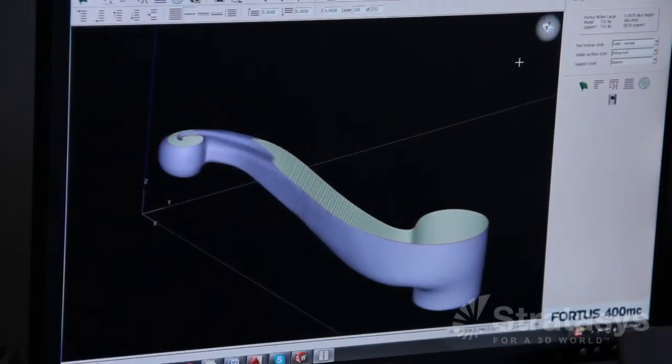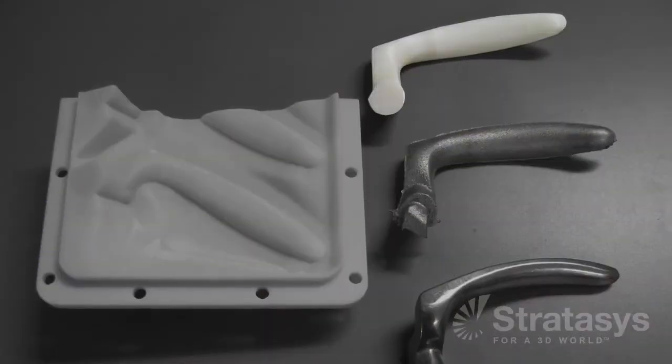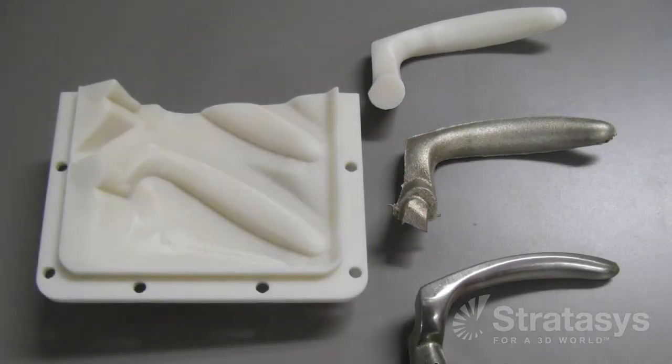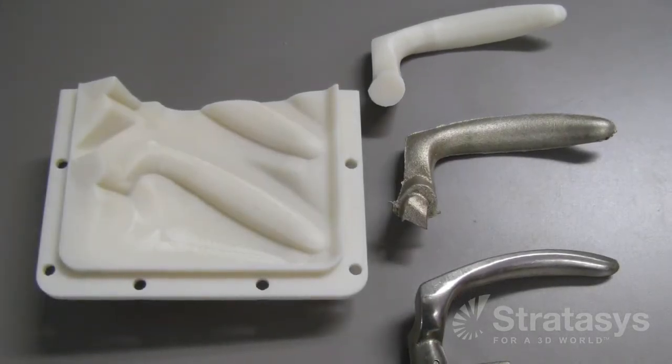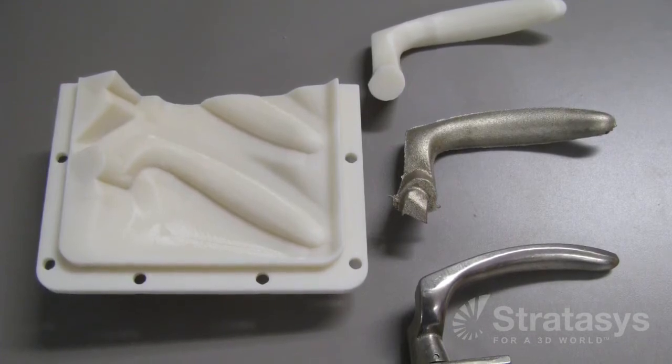Even before the foundry starts making sandcasting molds, it may benefit from using FDM to make models, prototypes, and sales samples of the castings to validate product designs and get customer approval to proceed with the order. With that approval, the sandcasting process begins, and it starts with pattern production.